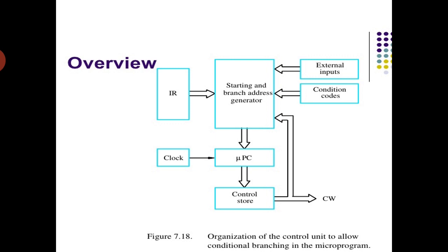So whenever an end micro instruction is encountered, the microprogram counter is loaded with the address of the first code word in the micro routine for the instruction fetch cycle.